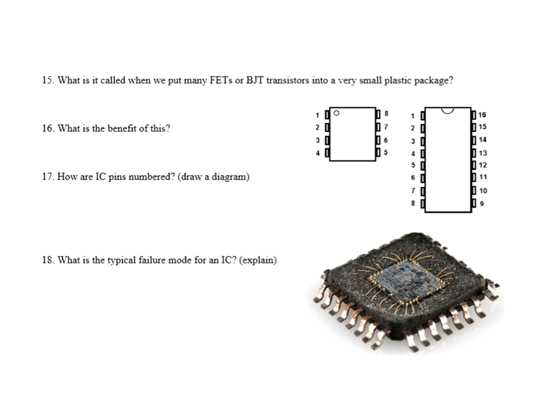Okay, now look at this. How do we number these pins? Do you remember how we number these? Looking down from the top, you're going to either see a little notch here or a notch here, a circle or a notch. And it makes me mad sometimes whenever you don't see that mark on there because then it's really hard to figure out what pin you're dealing with. But anyhow, you start here, then you work your way down, and then back up the other side. That's how you properly number them.